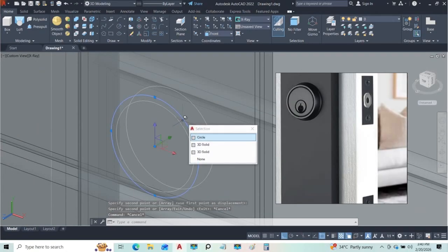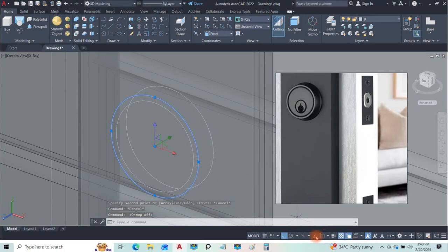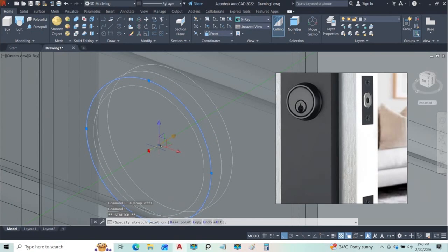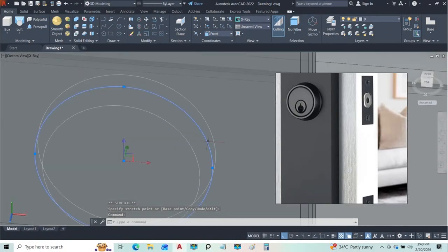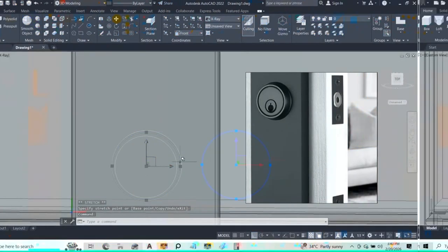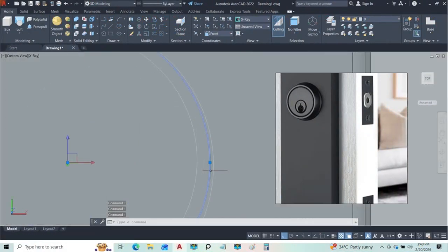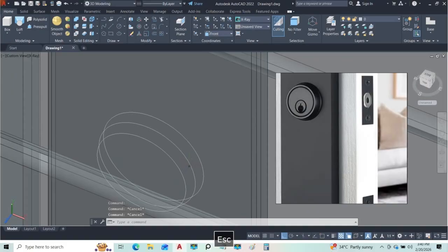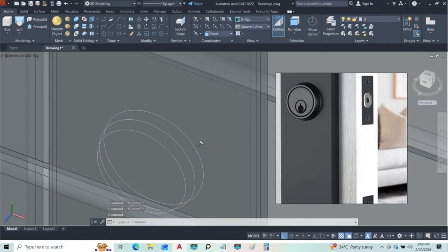So for this one, I'm going to move it backwards. So I just need to turn off my snap. I'll move it here. So you have something that goes here. I can also move this a little bit back down like that, so we can have that rounding going all the way. Just move it down a little bit, just a touch. So now we now have three shapes. So this will not be like a conical shape anymore, it will now be curved.